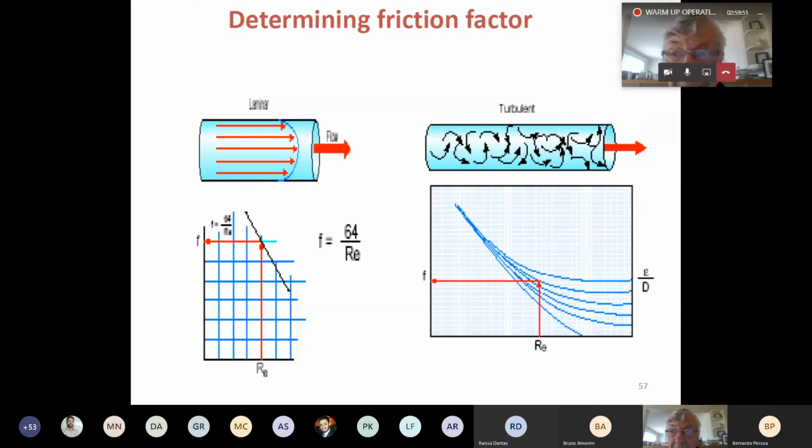If we go too slow, we'll find that there's a possibility that the heavier fluid can push through to the fluid in front, and you'll get contamination. So we've got to be very careful then. We like to work in the fully turbulent regime. So let's go to 58.